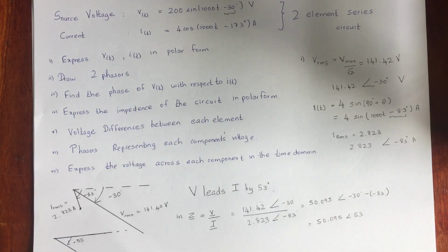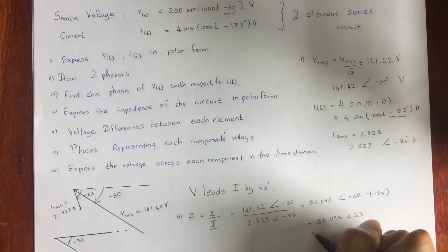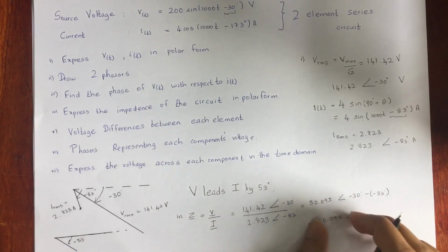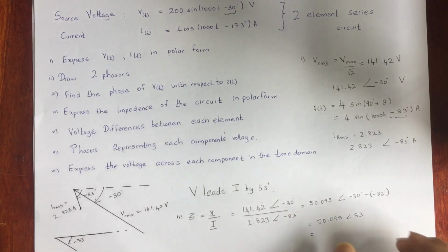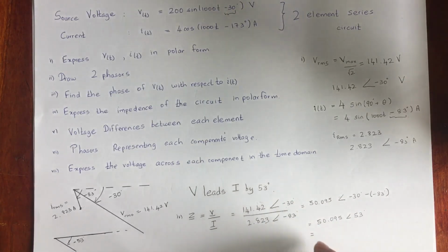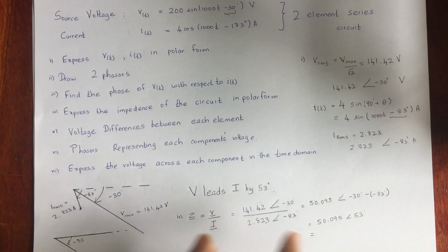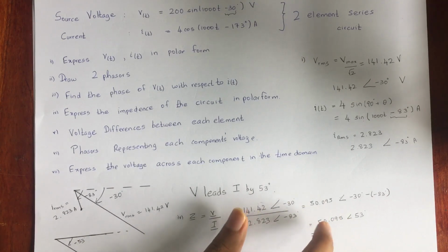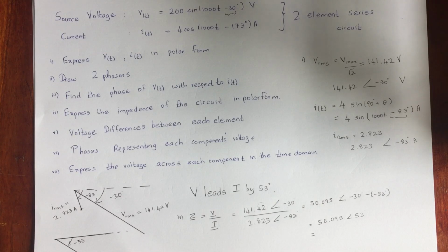From over here, if you directly divide this into two parts, resistor and reactance, we can tell that the resistance part is going to be in that resistor, and the reactance part is going to be in that inductor. So that's the part we are going to do for this one, to find the value of the resistor and the inductance of that inductor.